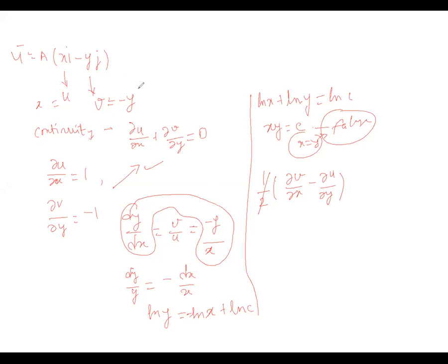In the v term, there is no x quantity. So dou v by dou x equals 0. Similarly, in u, dou u by dou y is equal to 0. So this equals 0, so the rotation component is 0, and therefore it is irrotational. That condition also has to be checked. Suppose the options are given in a different order, you have to check one by one.